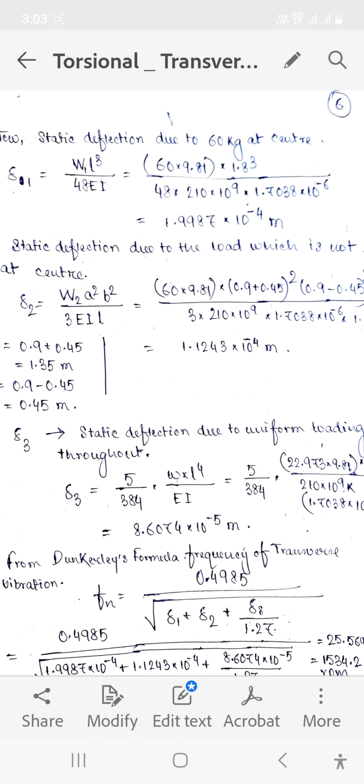Please understand that while finding out the frequency and the RPM, whatever you say, the deflections due to these loads are important. So first you have to identify whether it's a fixed bearing or flexible bearing. Then, depending on that, you need to consider the deflection expression. If it's a central load, then there will be one expression. If it's a uniformly distributed load, there will be another expression. If there is an offset loading apart from the center, then there will be another expression.